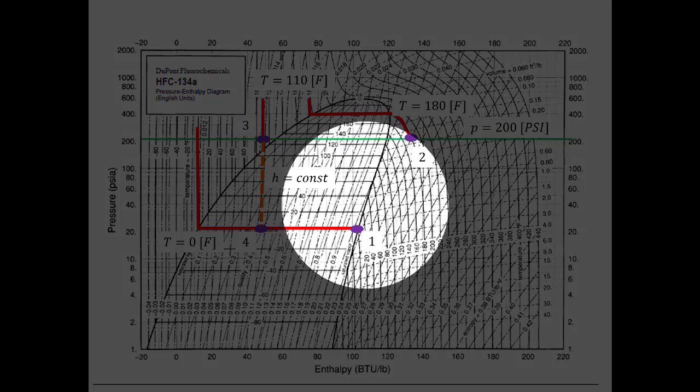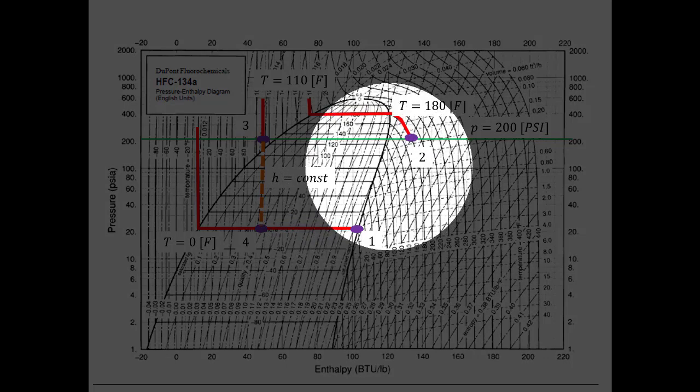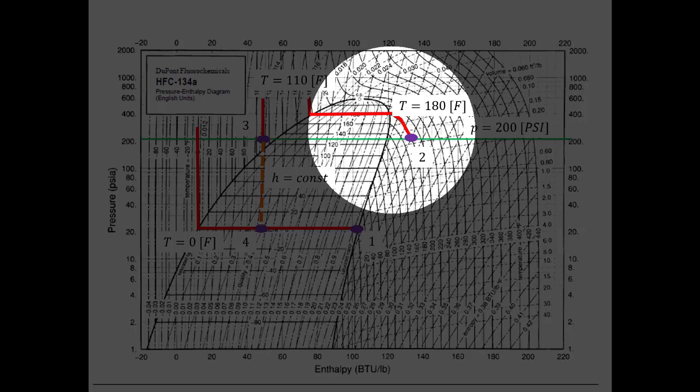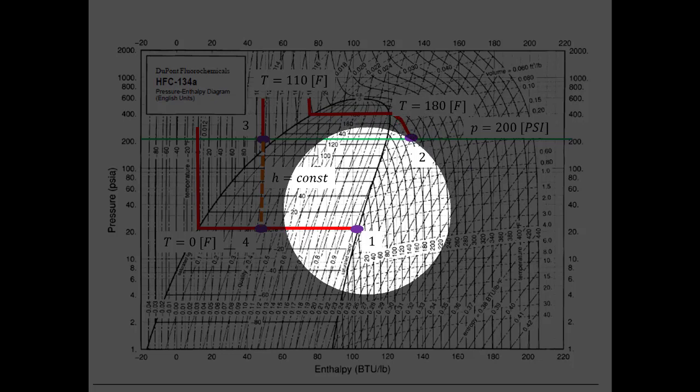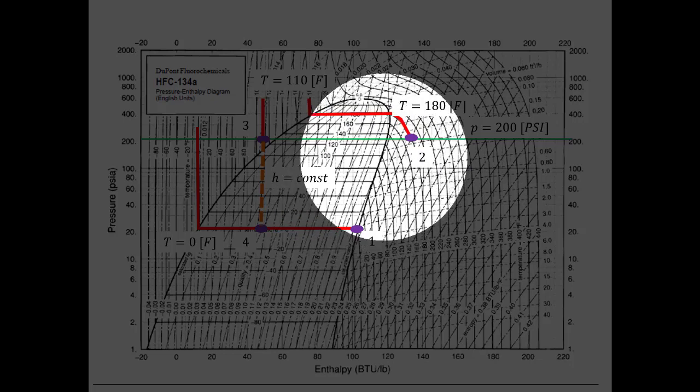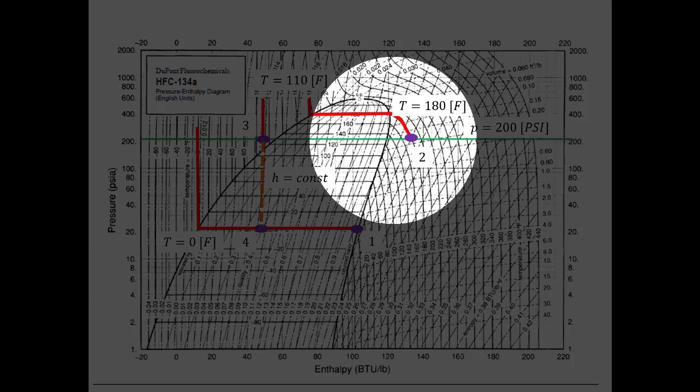You see the constant entropy lines are these ones that are slanting over here, but the slopes are changing, right? So here's one constant entropy line, and here's another one, and the slopes are a little different. So I've got to draw a line that kind of splits the difference on those slopes, and it's a constant entropy line that goes up, and state 2s will be somewhere in between those two lines, right?